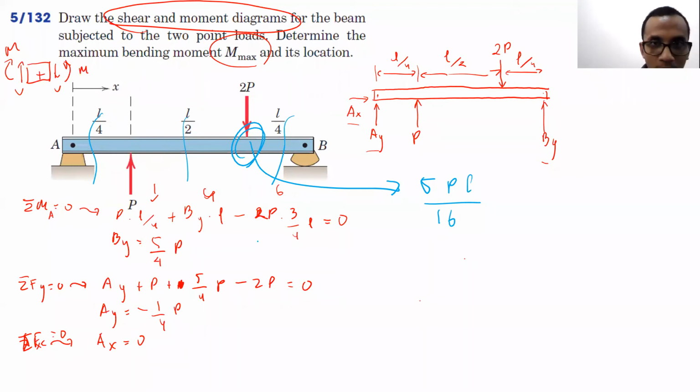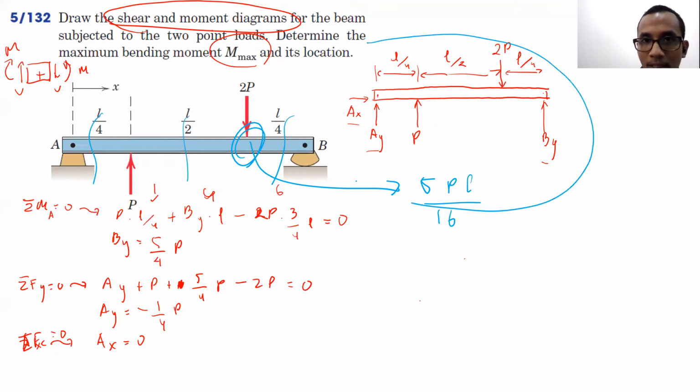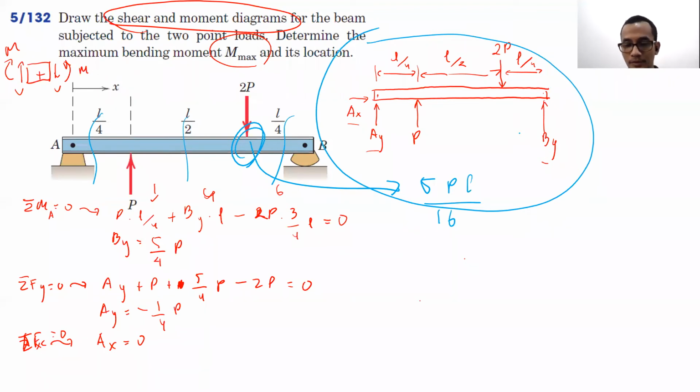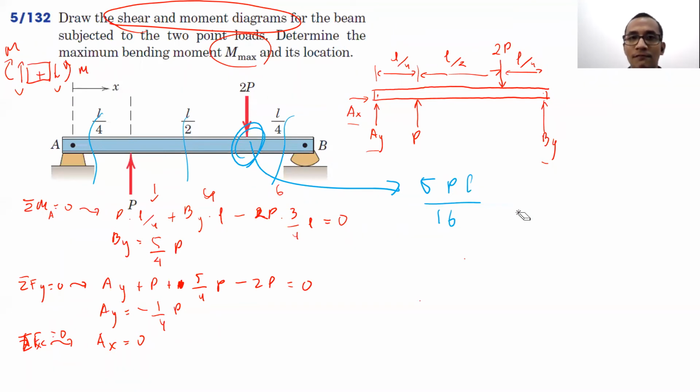So when we talk about this particular free body diagram, there is a concentrated load on the left edge, and concentrated loads here, here, and here. That's why our moment diagram has to follow that as well. The first section is supposed to handle the part between these 2 concentrated loads.